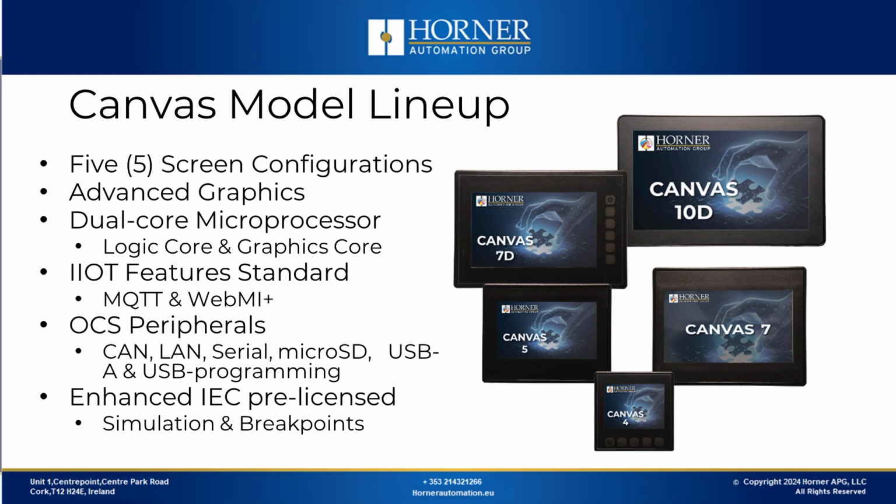In addition to the enhanced MQTT Sparkplug and WebMI IIoT type features, Canvas also has the ability to use any of our logic languages. So whether you prefer the traditional register-based advanced ladder or variable-based advanced ladder because of its user-defined function block capability and other capabilities, these are both supported by Canvas better than ever before. You can also use enhanced IEC with Canvas and some advanced type troubleshooting tools like breakpoints.